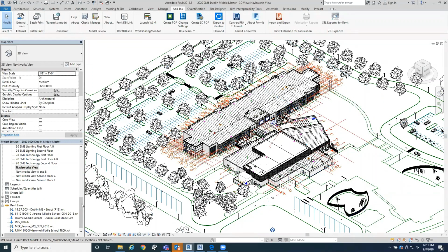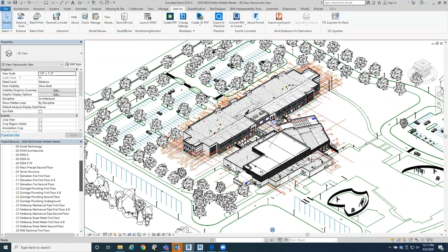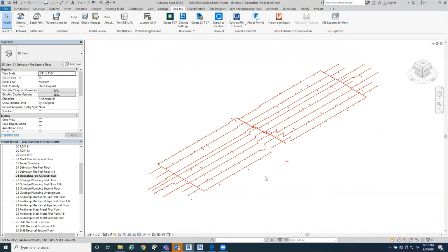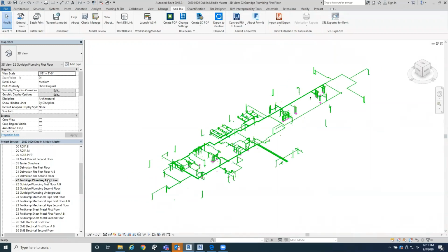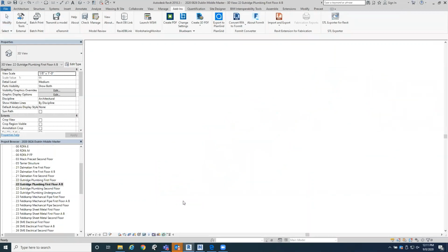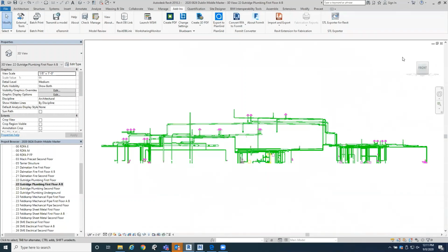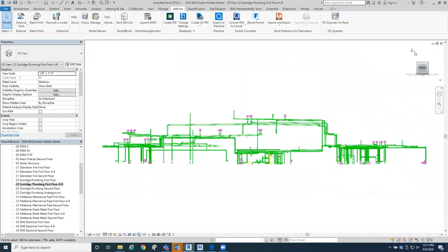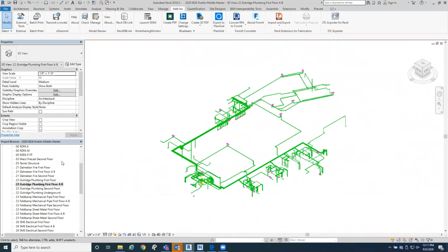So when I'm bringing everybody in to Revit, then it makes it easier for me to split up the floors and the sections the way that I want to see them in Navisworks and the way that we want to run clash detection with them.